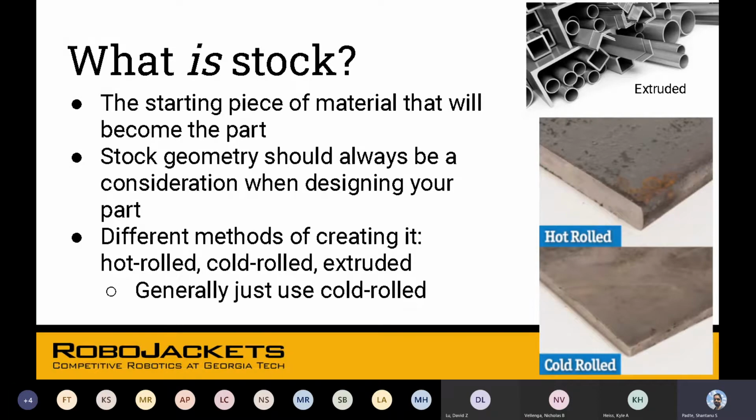Well, hot rolled usually refers to steel that has been just pressed at very high temperature. It's cheaper than cold rolled, and it's slightly more deformed than cold rolled steel. Cold rolled steel is, however, stronger than hot rolled steel, but because it takes more effort to make it cold rolled, it's generally more expensive as well. And it has tighter tolerances, and it's generally smoother.